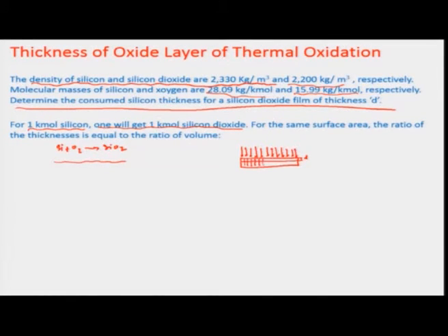Let us say we wanted to build up the cross sectional view of the cubic lattice of the silicon; we are talking about interstitial impurities of oxygen getting into the lattice structure because of bond vibration and also high thermal energy. So, these are the oxygen moieties being trapped within the crystal, oxygen is being diffused inside.